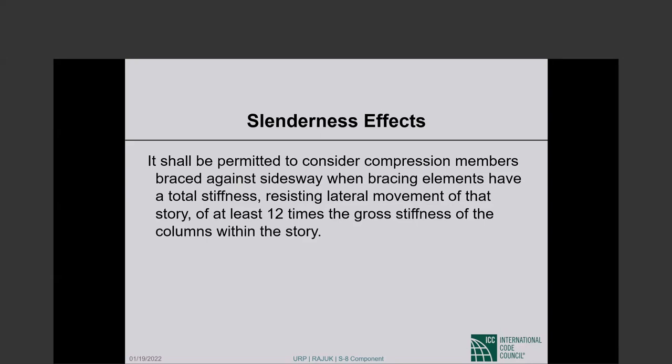When the building moves from front to back, there will be bending moment on the same column but in a perpendicular direction. We typically design buildings one direction at a time, so it doesn't necessarily have to be biaxial bending, but that's beside the point. My point is that there is an implied direction.